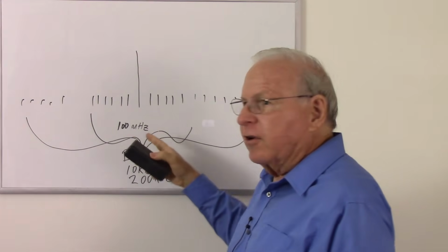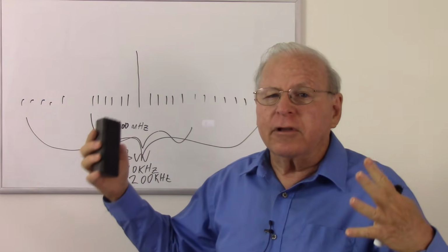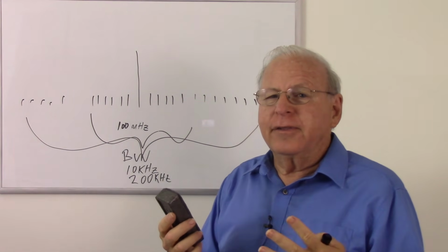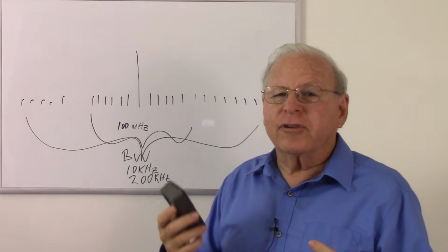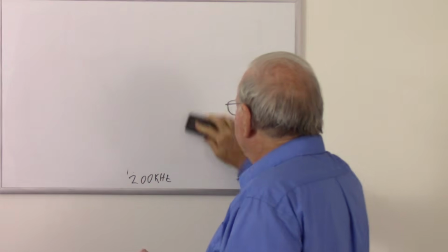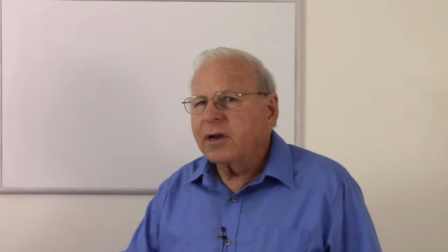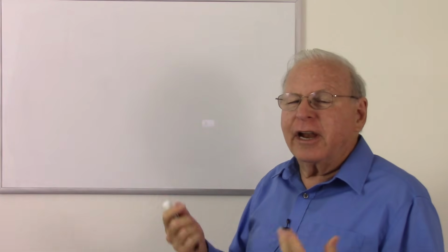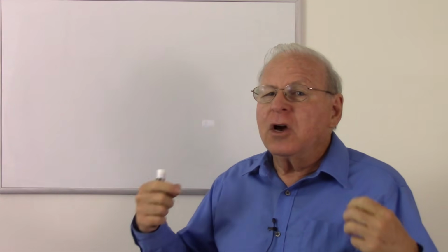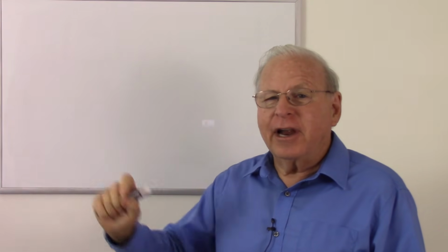So at the higher frequency, we have a greater bandwidth. Okay, now if we keep raising that frequency, we can have a greater usable bandwidth. So now we're talking about radio. What is light? Light is the same thing as radio waves, just much, much higher frequencies. At the frequencies, or should I say the wavelengths, used in fiber optics, remember wavelength and frequency are the reciprocals of each other, we're talking about 100 terahertz of our carrier frequency. So our bandwidth is absolutely tremendous. What does that mean? We can carry very, very high-speed data if we use light as our carrier.